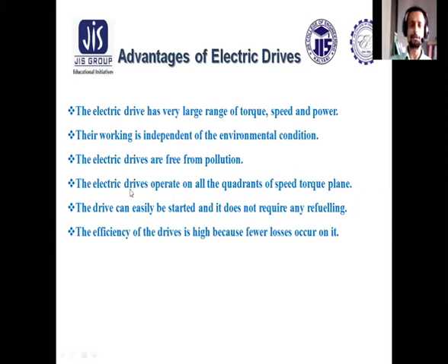The electric drive can operate in all 4 quadrants of the speed-torque plane. It can easily be started, and it does not require any refueling. The efficiency of the drive is high because loss is less, as there is not much involvement of large mechanical devices.